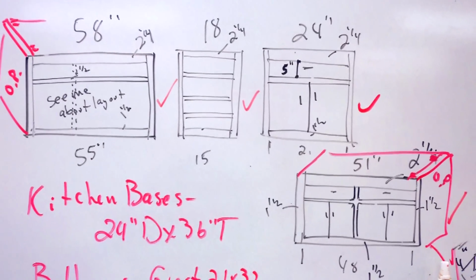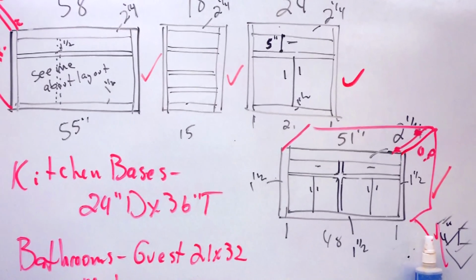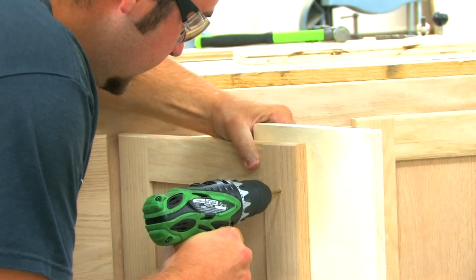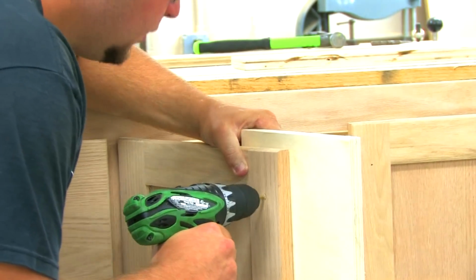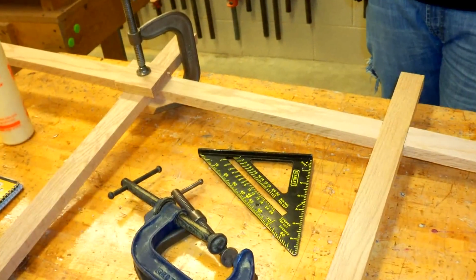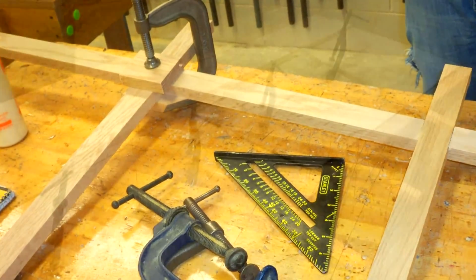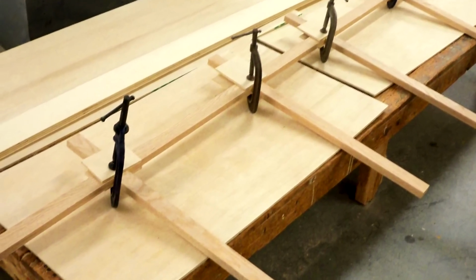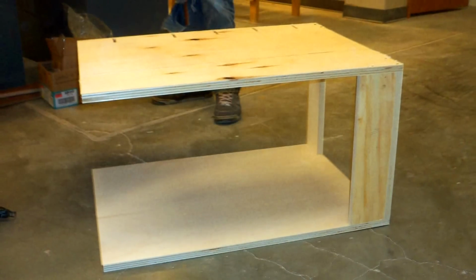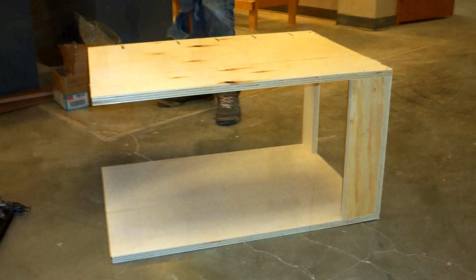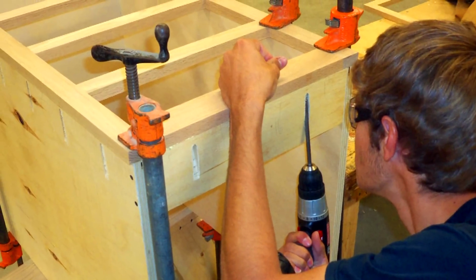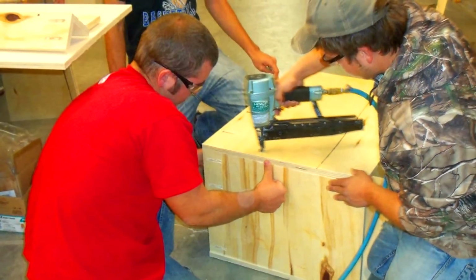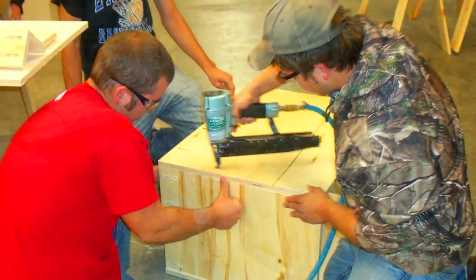Once the drawings have been examined and the cut list is made, the students are taught how to use the equipment in the lab before they begin any sawing, cutting, and sizing of the wood materials for the cabinets. First, the face frame of the cabinet is built, and then students size and saw what is called the standards, or the sidewalls. The floor is then fabricated, attaching the face frame, but making sure everything is flush, square, and sized. Once the cabinet is assembled, the toe kick is attached to the bottom of the cabinet.